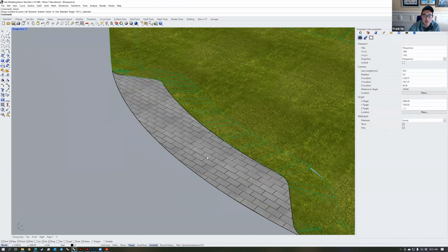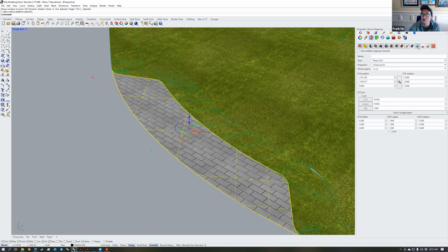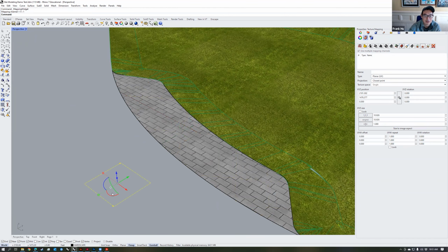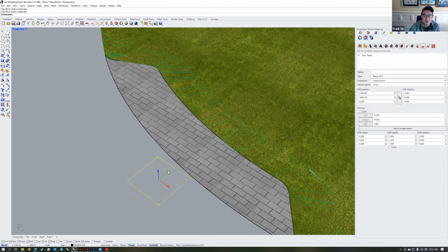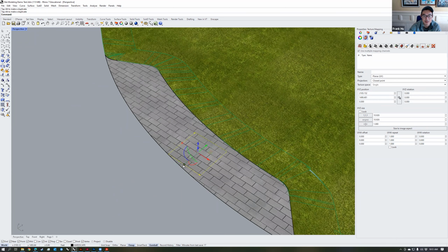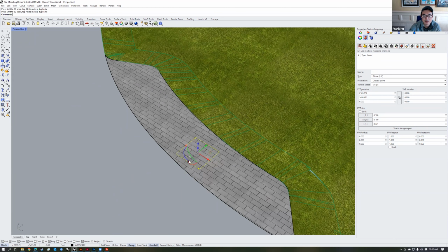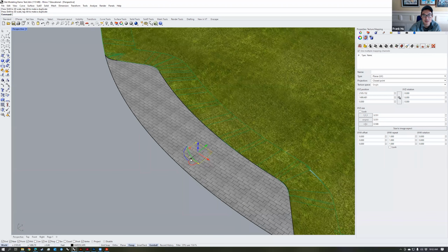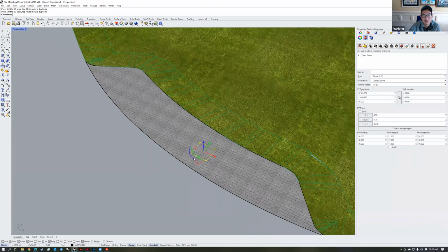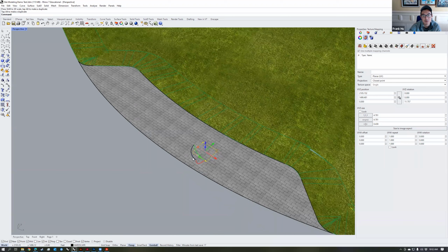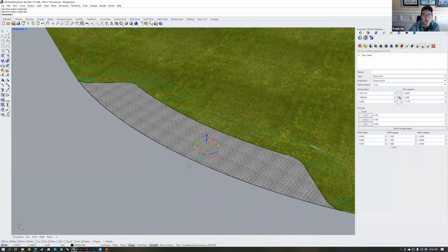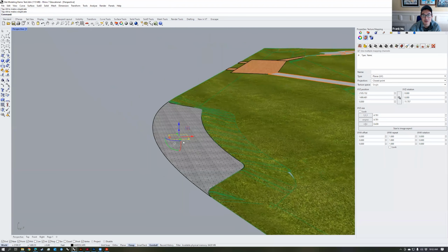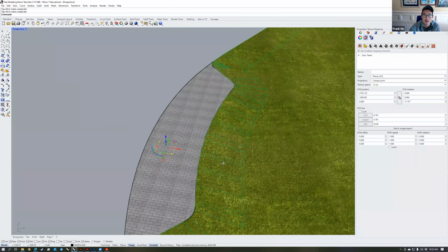Once you've set the texture map, just click on the option again, then choose this show mapping button in the texture mapping options. That brings up that square that you just drew. Now you see if you move that around, it moves with the map. And then you can scale this texture map to get the texture to be the scale that is appropriate for this. You can even rotate the map as well to align it with, say, for instance, something. Maybe this is the preferred direction for this detail. And then once you have your map set up, then you just choose hide mapping, and that goes away.